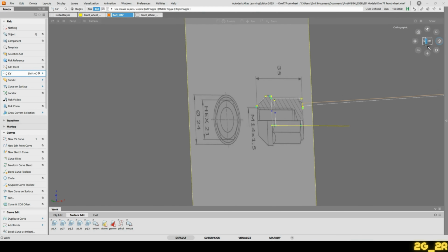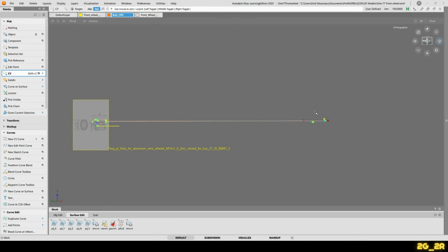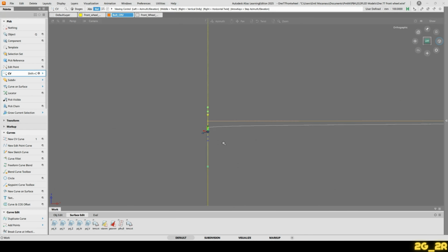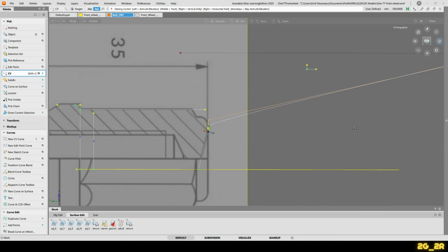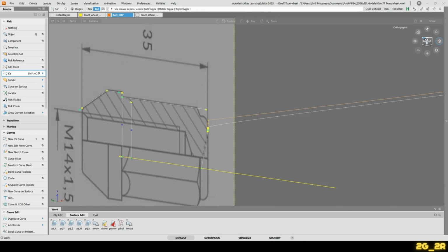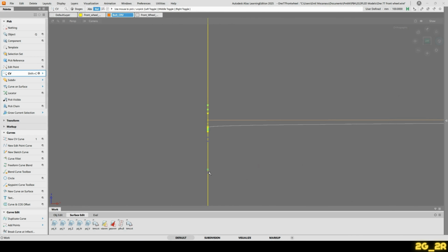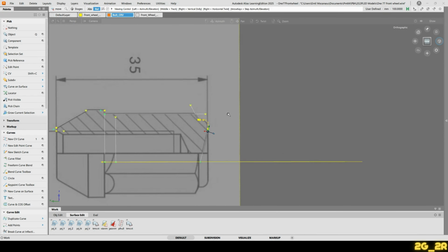And you see, I've built it a bit wrong. It's not all on the same plane, which is not a problem. I'll just snap all the CVs with Control and the middle mouse button next to this point here, so move tool and then Control, middle mouse button next to this one in this view, and it brings everything on that plane.